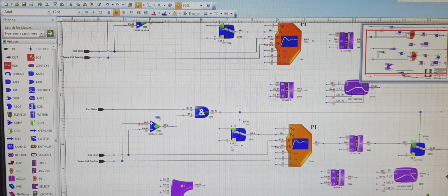So as you can see, in low occupancy or large volume spaces, a low level of CO2 cannot necessarily be used as an indicator that ventilation is sufficient to mitigate the transmission risks. So we have to consider ventilation as a part of hierarchy of risk controls approach. So that's what we're going to discuss today using our Alerton program, how we can control the dampers. It could be the VAVs, implemented in VAV strategy. That's what we're going to look here on the program. And also we will look at the ASHRAE guidelines of how it is to be controlled and the strategy we